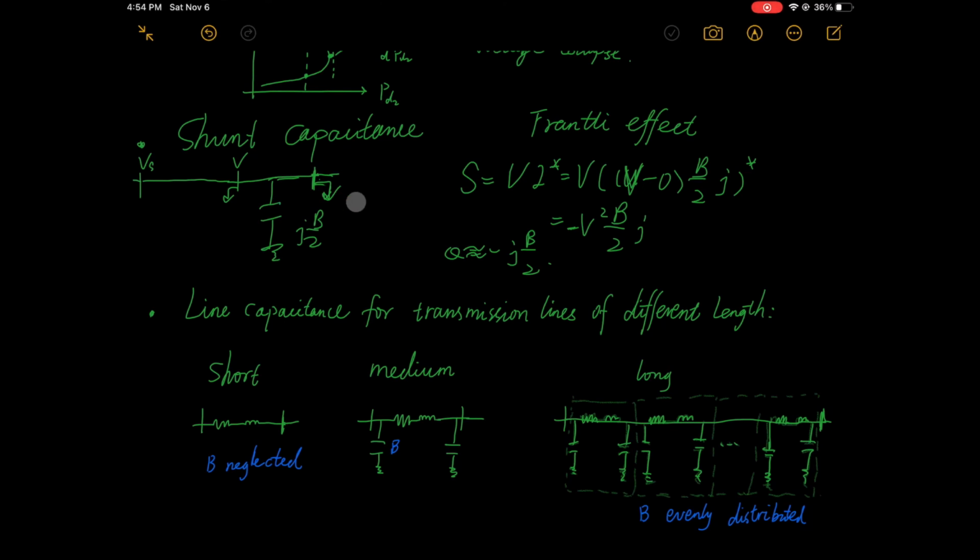By leading or lagging, we mean how current and voltage angles are related. For example, according to physical laws, voltages of inductive devices are proportional to derivatives of currents, so V is proportional to omega j i, which means current lags voltage in the phasor plane.